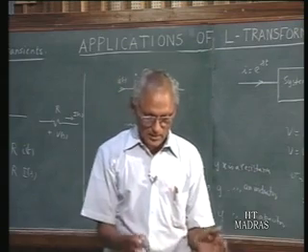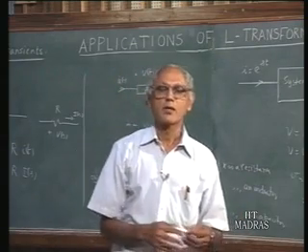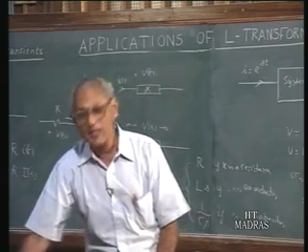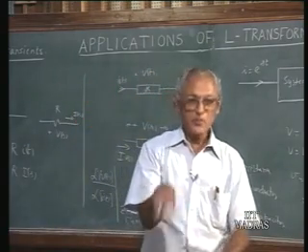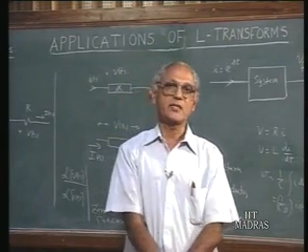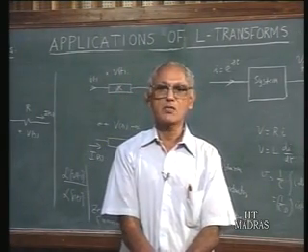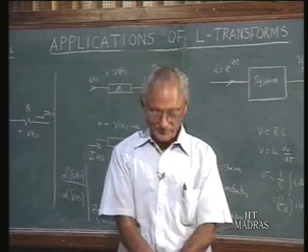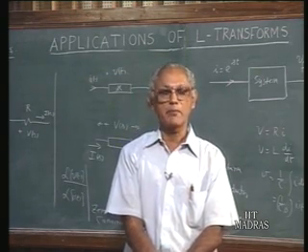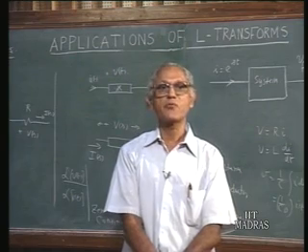We have a general circuit that is given to you. Instead of dealing with i(t) and v(t), sinusoidal voltages and currents, we represent in the circuit diagram the impedances of the various elements, j omega L, 1 over j omega C, as the case may be. And instead of the raw currents and voltages in time domain, we represent them by means of phasors.